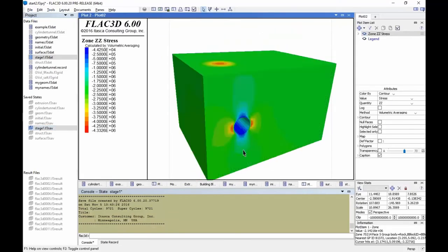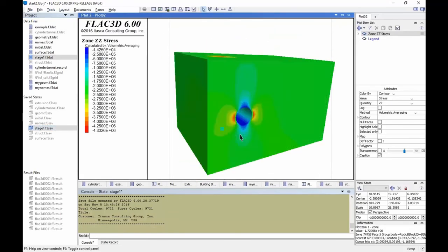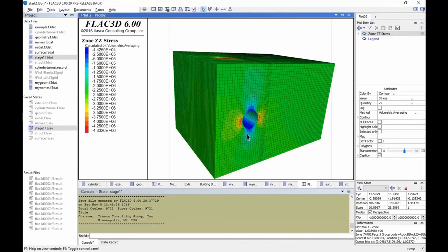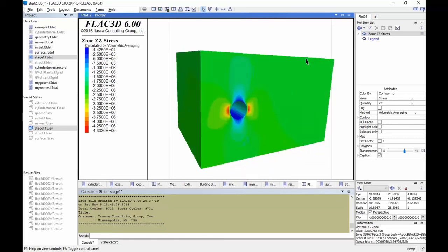All right, now here is the result of that, where you can see it. Now I'm going to do a little aside to talk about convergence issues. Note that we just use the standard model solve, which is what we call an average ratio, which means that on average the grid points are converged, but any individual grid point might not be converged.